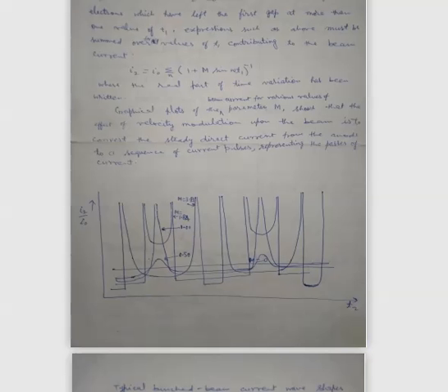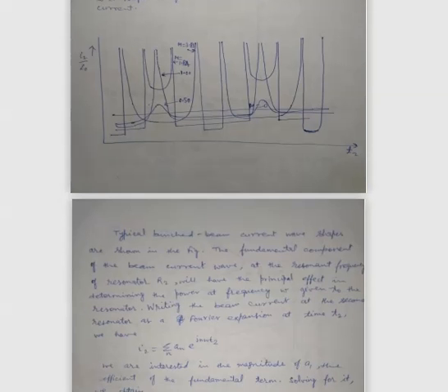So this equation for I2 will give us the current as a function of time, and due to the presence of sine omega t1, sine twice omega t1, etc., it means this current is a pulsed current. If we plot I2 over I0 versus time t2, this will give us the pulsating current graph for different values of the bunching parameter m.